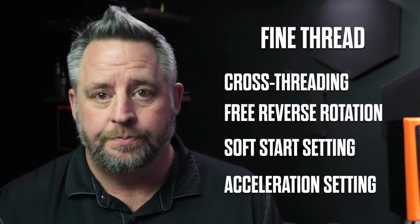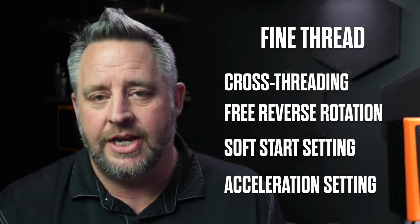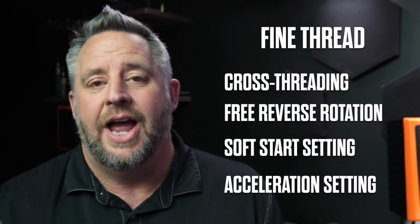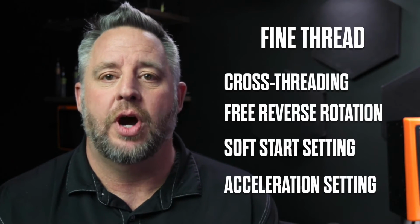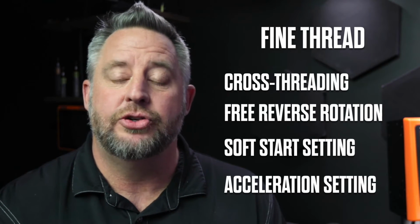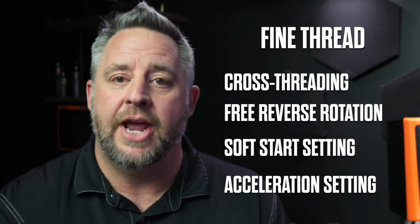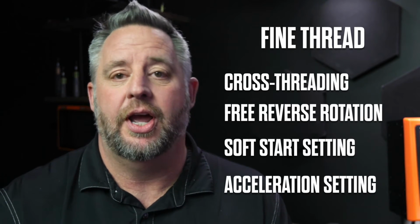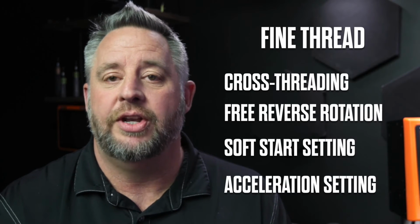And then go ahead and do our rundown. We also have the ability to have a soft start setting within the program. So as we go from our reverse direction to our tightening direction, we have the ability to have a very smooth and even transition. So when that transition happens in the rundown, it's not real abrupt, again allowing that thread to really find itself and run down.